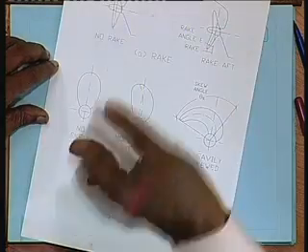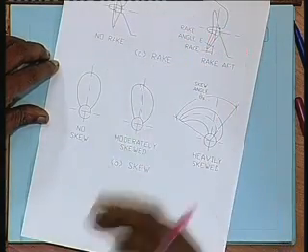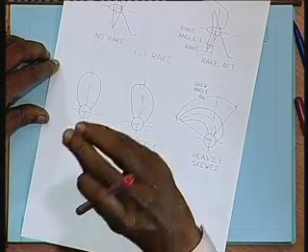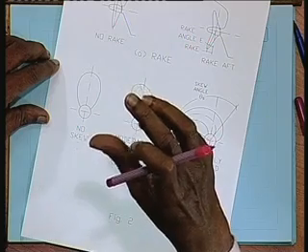Between rake and skew, rake also increases the gap in both the ways. Skew may increase the gap, but may not, because skew is actually in this plane. So, when the propeller blade rotates, at some place the gap may reduce, some place it may increase. But of course, a well designed, a well skewed propeller may actually improve the gap.